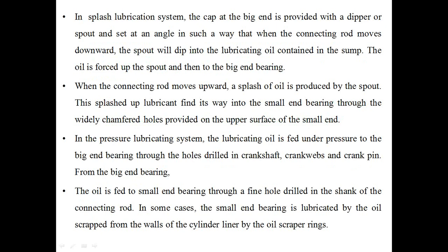In the splash lubrication system, the cap at the big end is provided with a dipper or spout and set at an angle in such a way that when the connecting rod moves downward, the spout will dip into the lubricating oil contained in the sump. We know that in an IC engine, lubricating oil is always present in the sump, which will cool and lubricate the piston liner also. The oil is forced up the spout and then to the big end bearing.